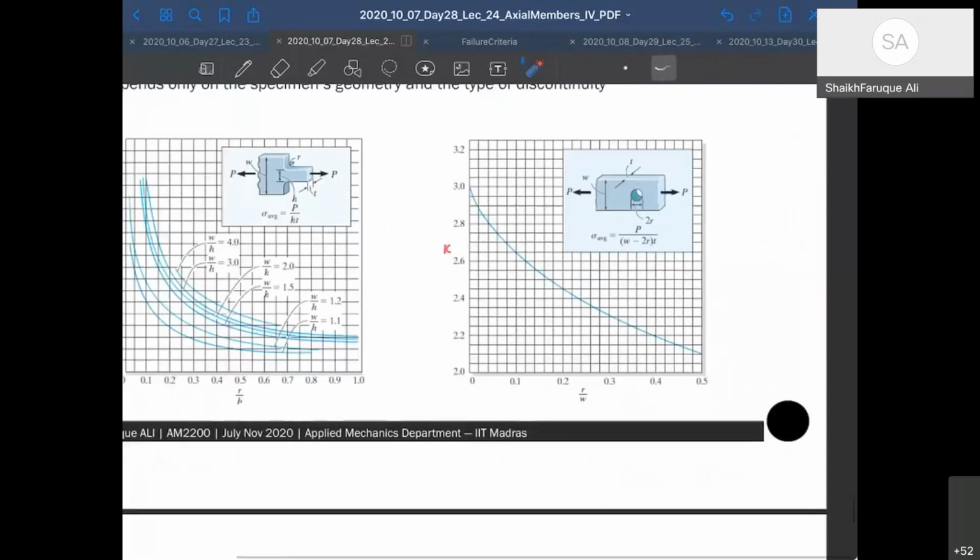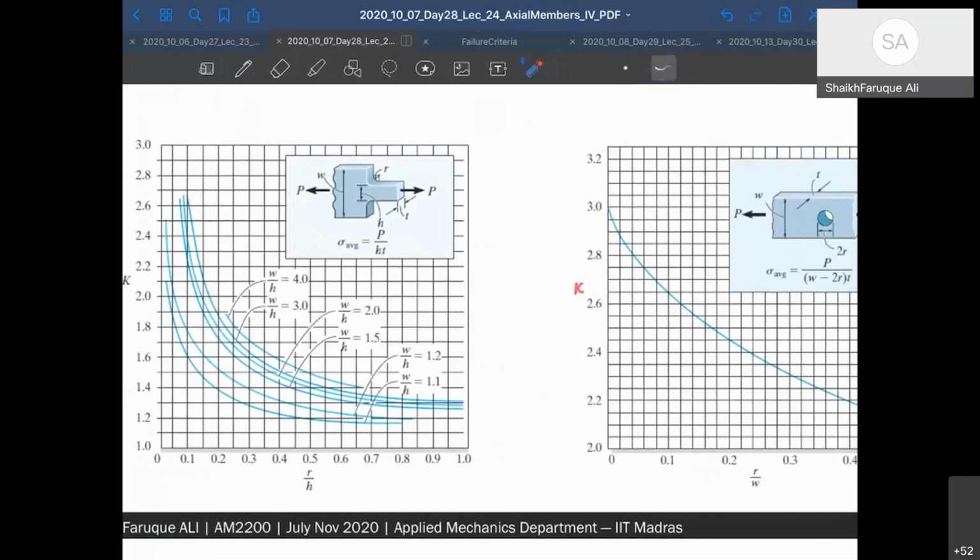What you do is, when you design your structure, you know your R, or you need to, let's say, find R. Okay. So you got a sigma average at this cross section or at this cross section. Once you know the sigma average, you know your maximum sigma y or yield, design yield. You know that. What you have to do is you have to find R such that your sigma max is lesser than your design yield.